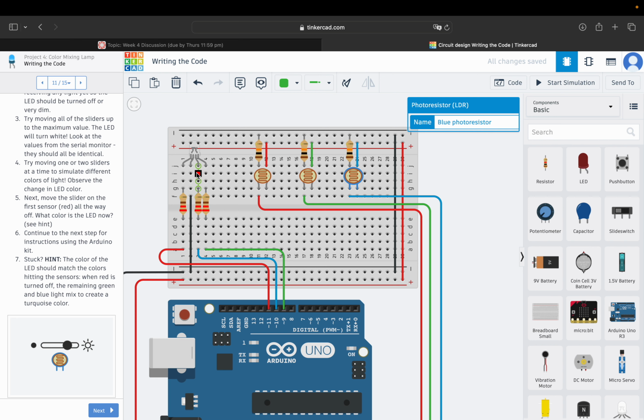And let's say if my room is red in color, then maybe I want this LED light to turn something other than red. And if my room is yellow, then I would like this LED to turn into some color other than yellow. So I make use of the photoresistors and the resistance to change the brightness of the color that it shows. And the ratio of time the LED is on and off determines how bright or dim the LED appears, and this is called pulse width modulation, which I used in this example.